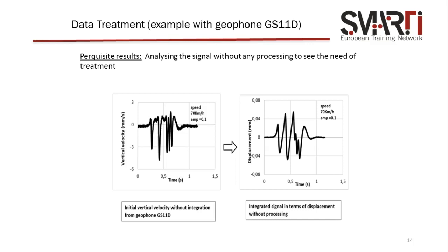Just to give an overview of the signal processing that we did. This is just the vertical velocity of the geophone, and that is the simple integration that we did to get the displacement values. But the results had these upward lifts, which were not related to what we did.